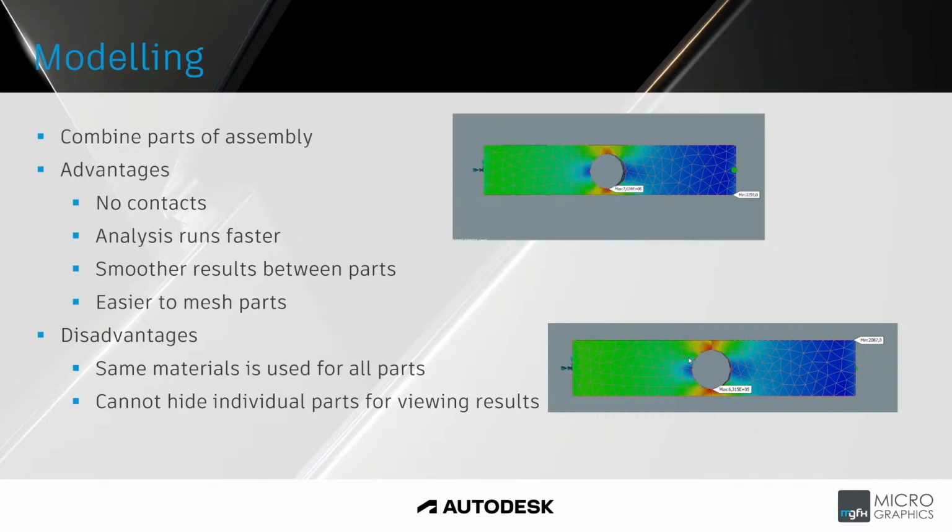Okay. One thing you'll also find is that it's much easier to mesh parts. So with the meshing of parts, you might have, say, 10 different parts, and those parts might vary in size from very large to very small in comparison. So what happens is, normally we say, right, this is the mesh that I'm going to have, and you have one size element, and Nastran will try and put that one size element on all your components.